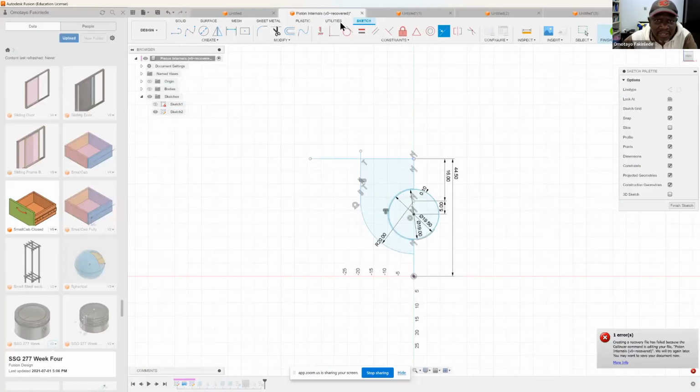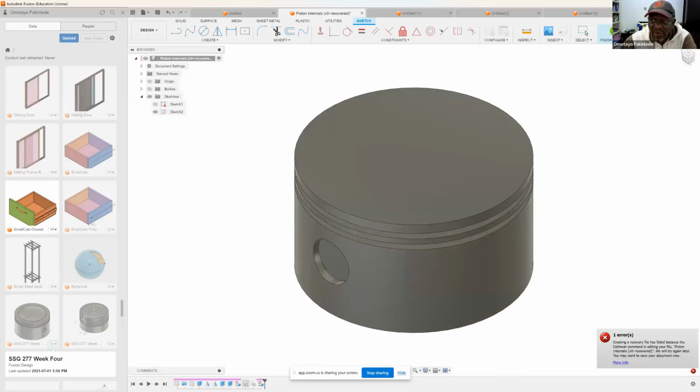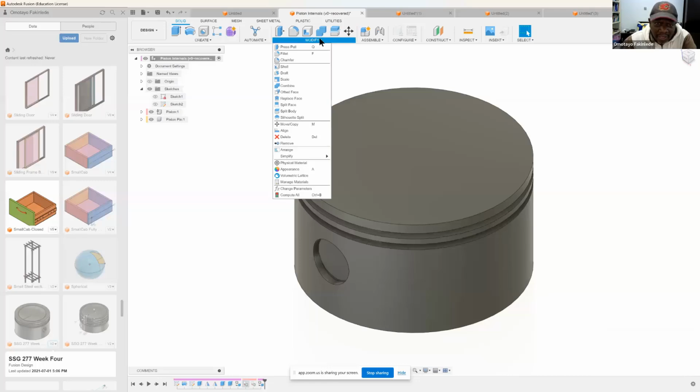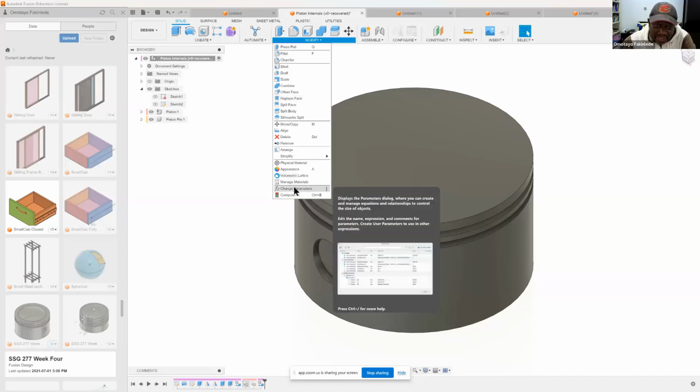In Fusion 360, in any situation, if you are not in Sketch or doing anything, you can just take your Modify, and use the drop down and go almost to the end. The second to the last item there is called Change Parameters.